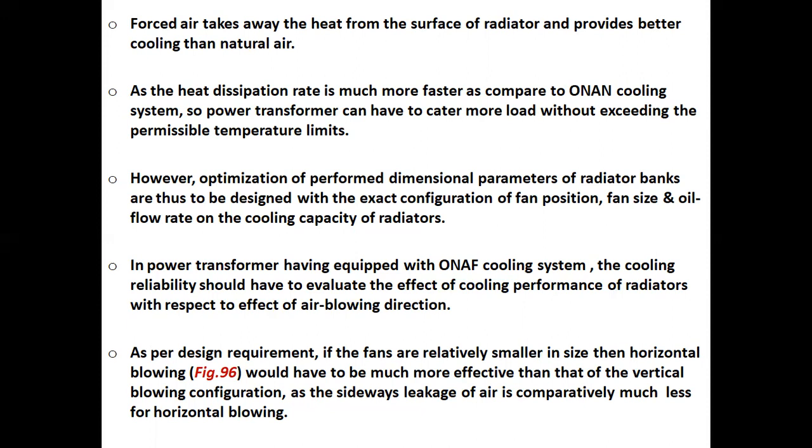In a power transformer equipped with an ONAF cooling system, the cooling reliability should evaluate the effect of cooling performance of radiators with respect to the effect of air blowing direction. As per design requirement, if the fans are relatively smaller in size, then horizontal blowing, that is in figure 96, would be much more effective than the vertical blowing configuration, as the sideways leakage of air is comparatively much less for horizontal blowing. So, in horizontal blowing, the size of the fan is much smaller.